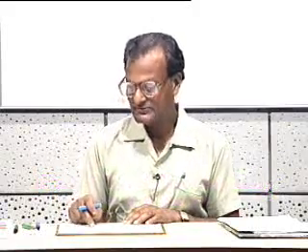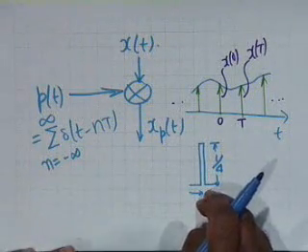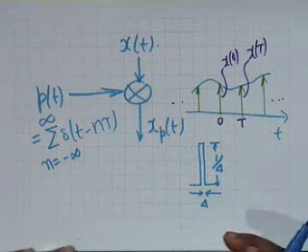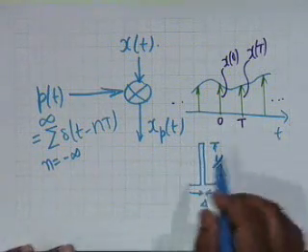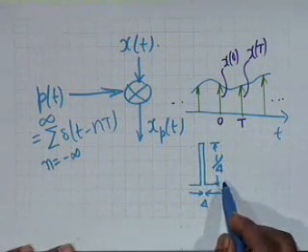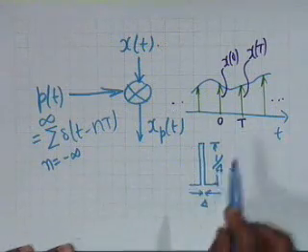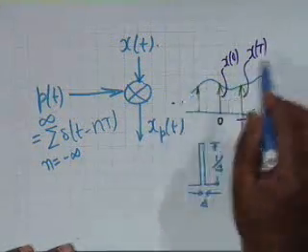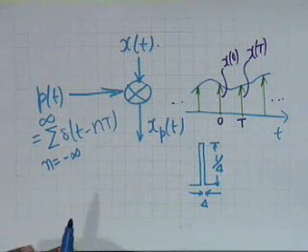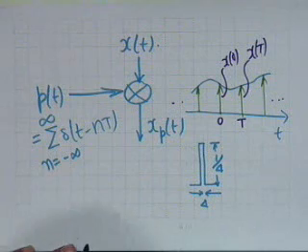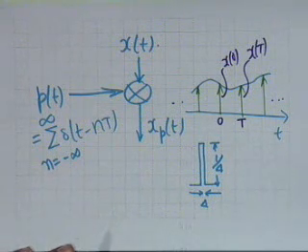You shall see later on in your course in communications that this amounts to very little distortion if delta is sufficiently small. As far as the spectrum is concerned, the resulting spectrum, when a function is sampled with a sequence of pulses like this, is simply the spectrum of ideal impulse sampling modulated by a slowly varying spectrum, which for all practical purposes can be ignored.